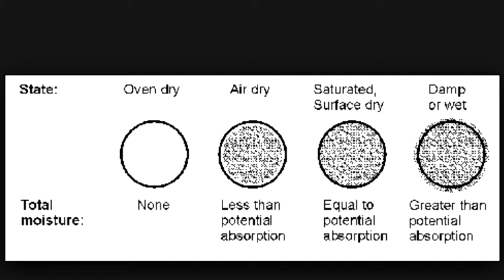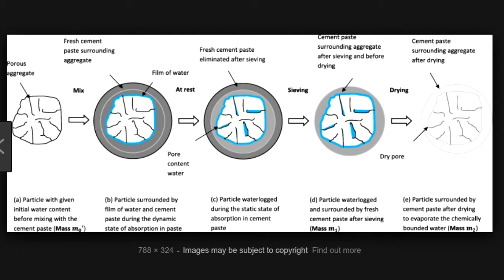For this experiment, we are trying to find the moisture content of aggregates. This test is important for strength and durability analysis of concrete. It is also vital for concrete production to know how much water is needed to be added to a mixture. A high water-cement ratio will weaken the concrete, while a low water-cement ratio will strengthen it. This method is sufficiently accurate for usual purposes, such as adjusting batch quantities of ingredients for concrete.